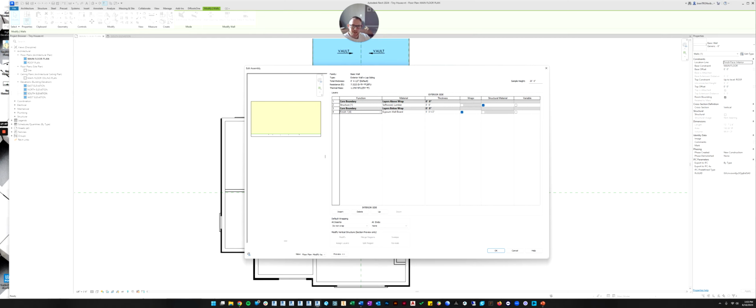All right, now we need to add our exterior material. So let's insert another material and let's move it up into the correct position. So we're moving it to the exterior side because this will be our exterior finish. Now it's up to you how many layers you want to add. Because I'm an architect, I add all of the layers that you're going to need. So technically, if you're going to put siding on an exterior wall, the first thing you put on the exterior side after the lumber is you put plywood, right?